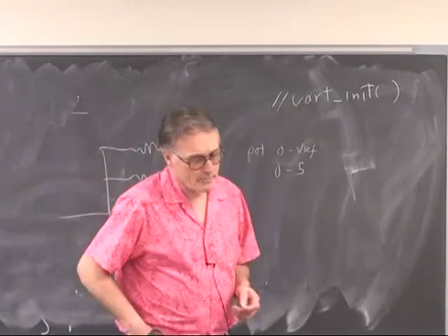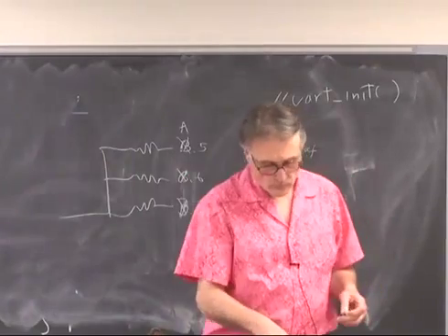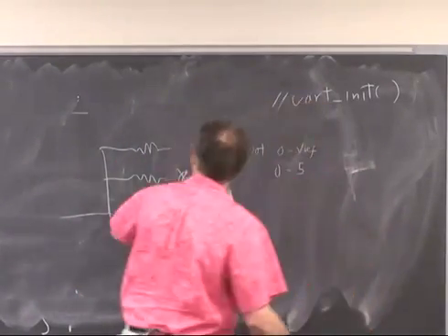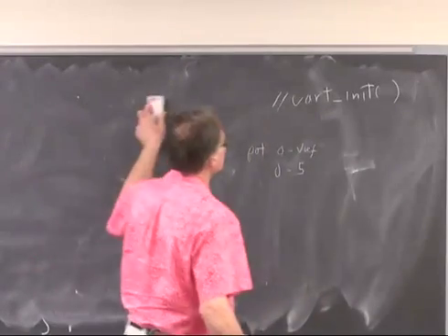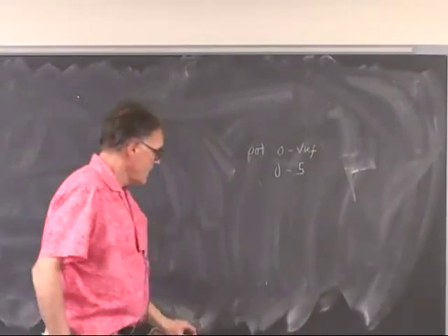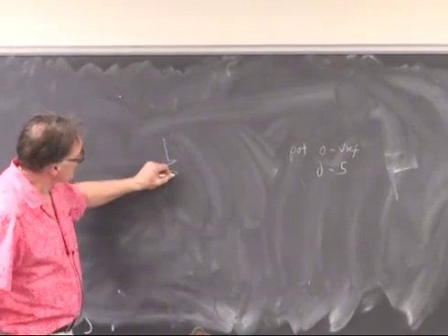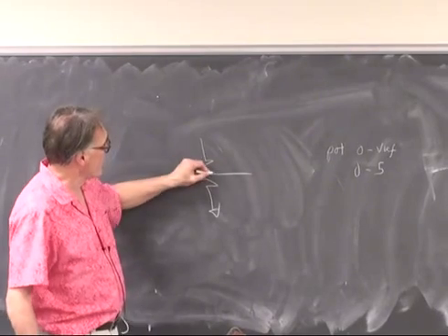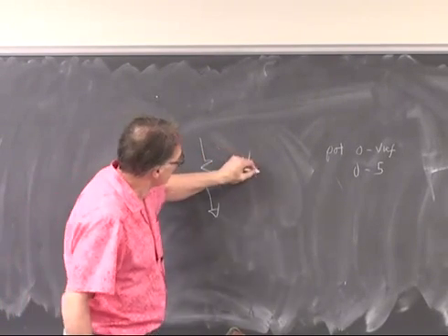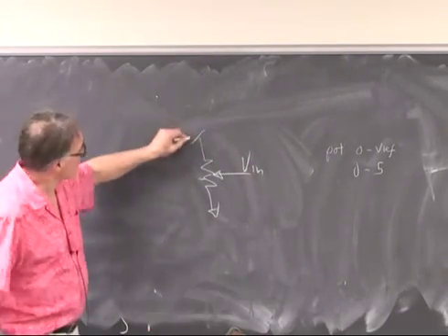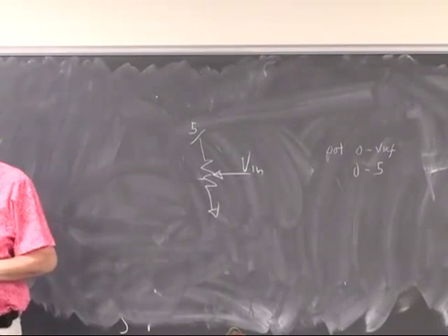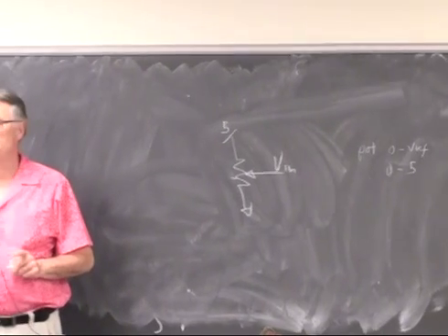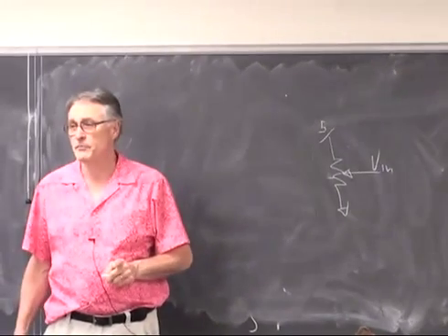So let's talk about keypads. Oh, one other thing before I start talking about keypads. What I specified on the board is that you could hook up a trim pot for measuring voltage, Vin, to +5, and that will certainly work, particularly if you're on the 5-volt full scale VREF.